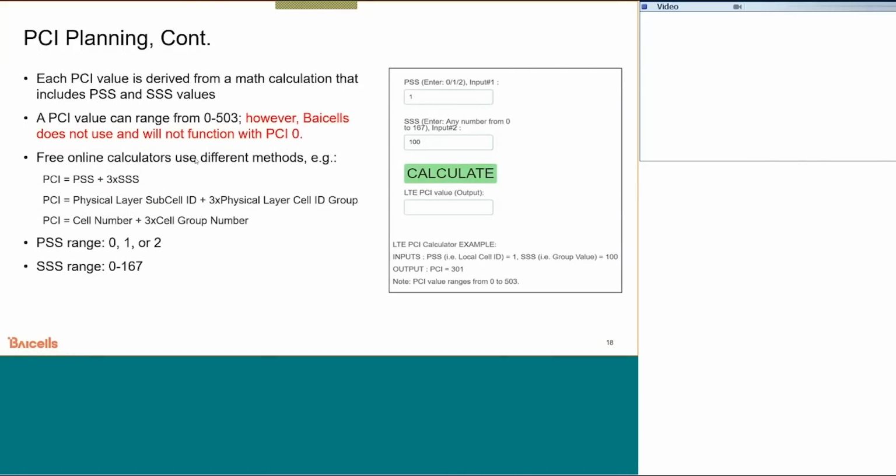Doing a lot of optimization, I see that people are having interference issues, and most likely the first thing I look at is how they do their frequency rotation to see if there's any overlap between adjacent cells. If I see any of that, that's a sure sign you're going to have problems.